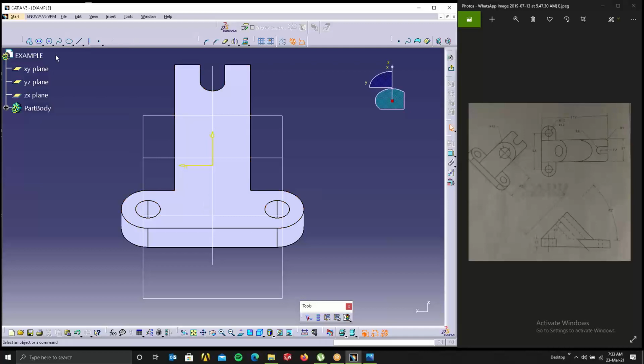First we'll do this. At the center point, we'll create one large circle, then one smaller circle at the same center point location. You can see this is exactly touching this. So I'll take project 3D element and select this edge, so I got a line here.